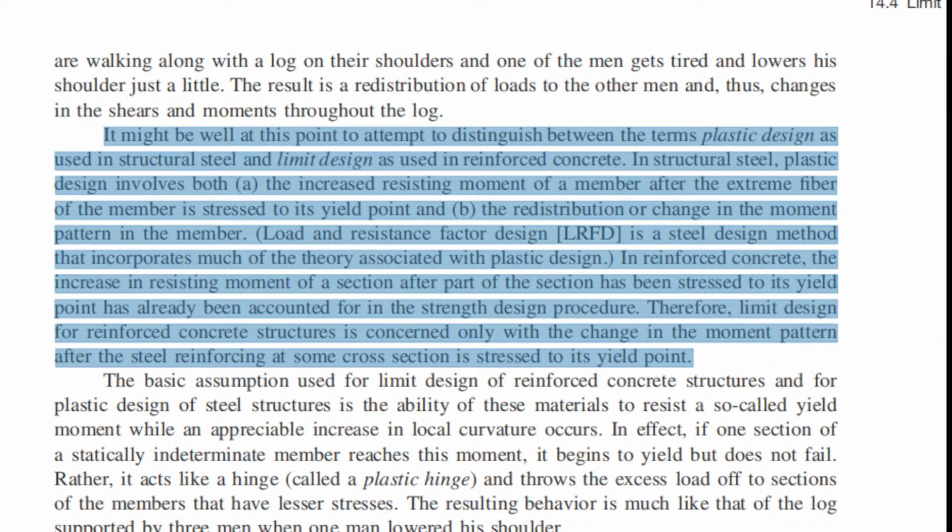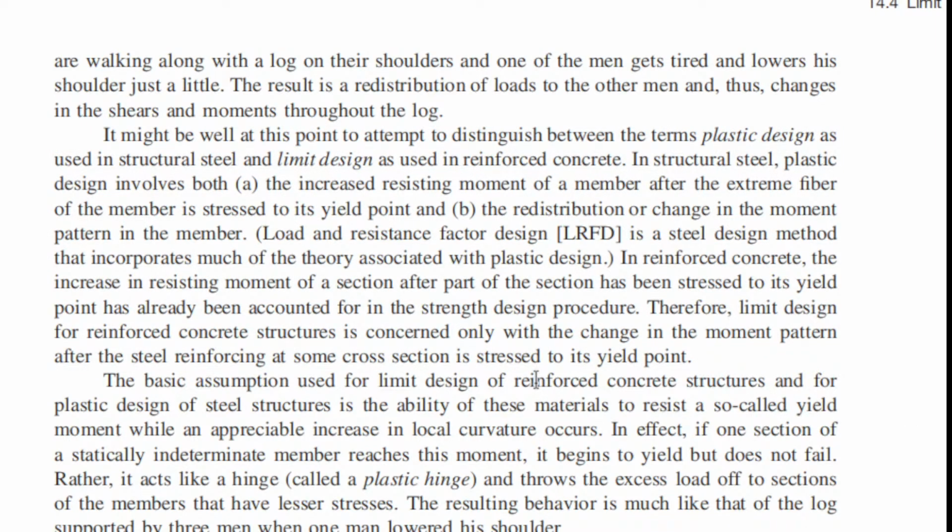Okay, so the basic assumption used for limit design of reinforced concrete, therefore, for a plastic region, is the ability of these materials to resist a so-called yield moment while an appreciable increase in local curvature occurs. Local curvature. This is what we mean by angle when we are talking theory of structure.